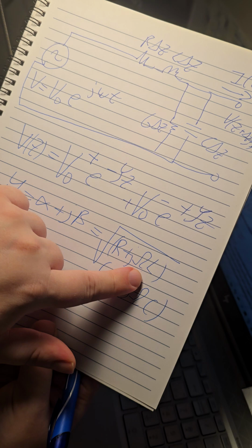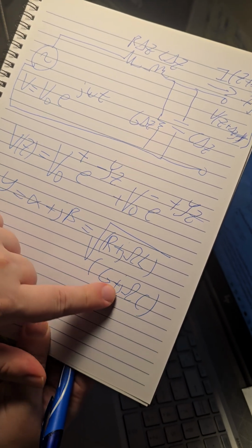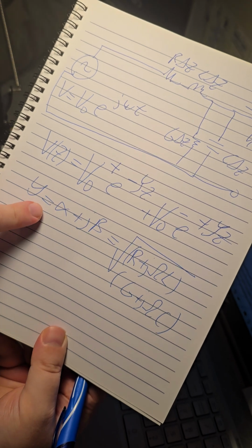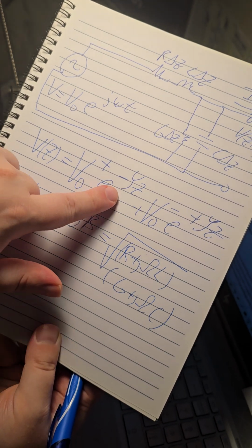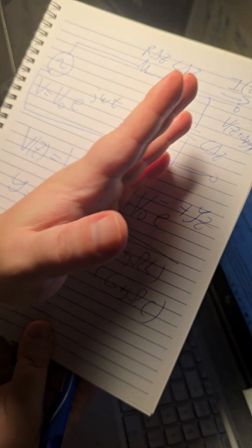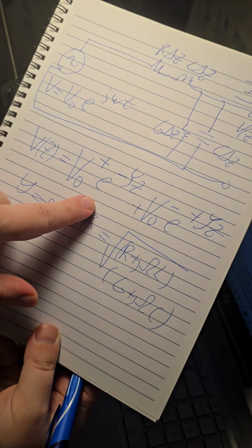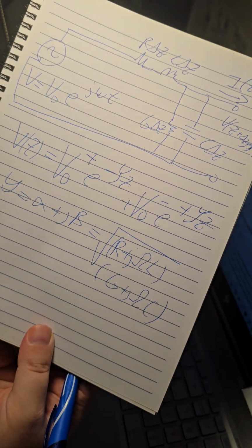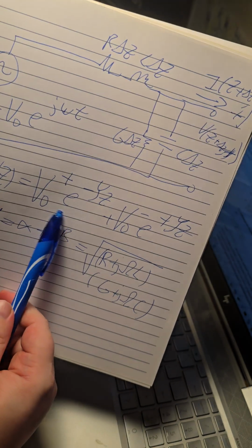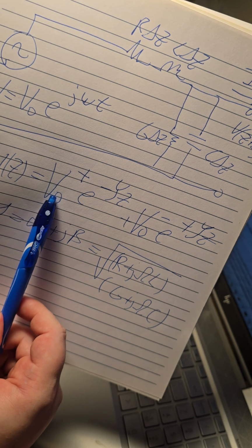And when you group them into a binomial of R plus jωL times G plus jωC, take the square root of that, that's going to equal alpha plus j beta, which is our gamma. And then you have e to the gamma z. So you always need a location. So at the location z, we have a forward wave times our scaling factor with z. And this kind of changes the phase. So this is the phase. This is the phase. And that's the amplitude.